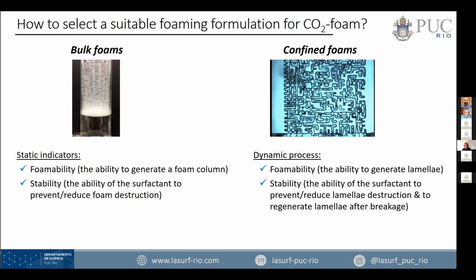Now foamability is related to the ability to generate that lamella, while the stability can be measured as the ability of the surfactant to prevent and reduce the lamella destruction and to regenerate the lamella after breakage, which is a big difference with bulk foams. So we have to look at different phenomena, even when the basics of formation and destruction of foams are the same in both cases.